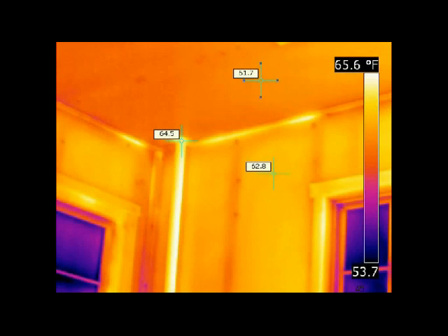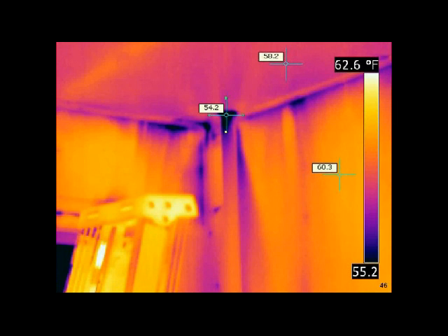Once we turn the infrared on, we take another look at it, and we can see some temperature profiles of the building, highlighting the plumbing stack. We've got some issues with top plates and a temperature difference between the exterior walls and the ceiling. Once you turn the blower door on, the assemblies really come to life, and this is kind of a classic shot of the telltale signature of an air leak with kind of a brushing effect or tendrils or whatever you want to call it. But the air leaks come to life. That's the beauty of infrared with blower door.